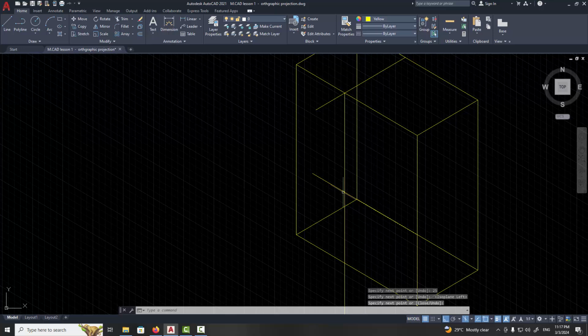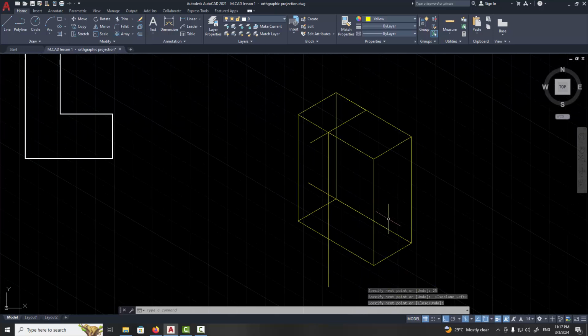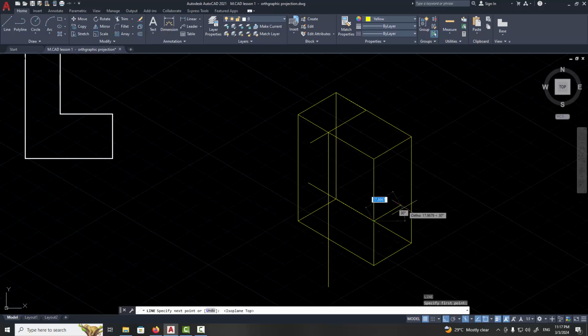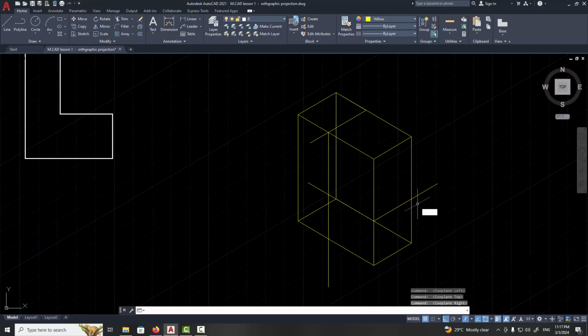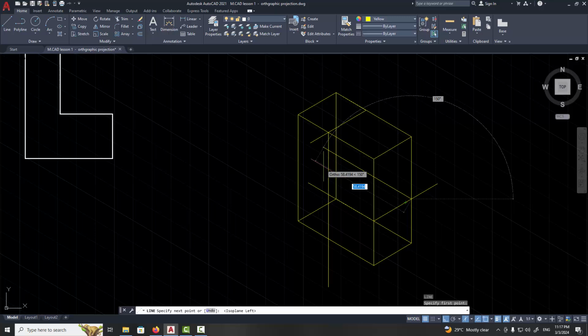Go back to the 25 unit point where you extended from the base, then move to the side to form your front part and extend beyond. Change the plane where necessary. Finally, where it intersects, I can draw a line going inwards to create this part.